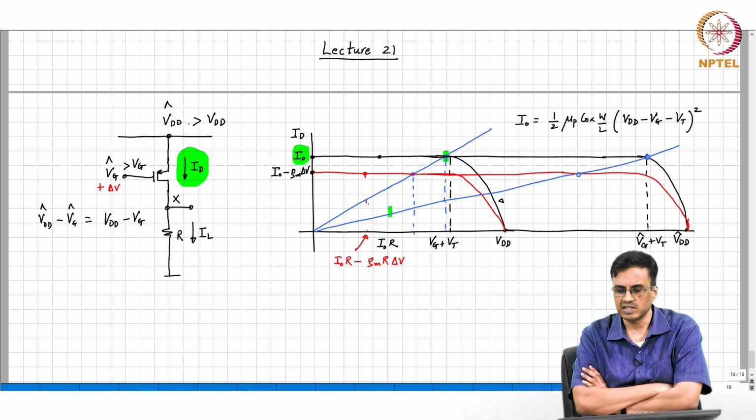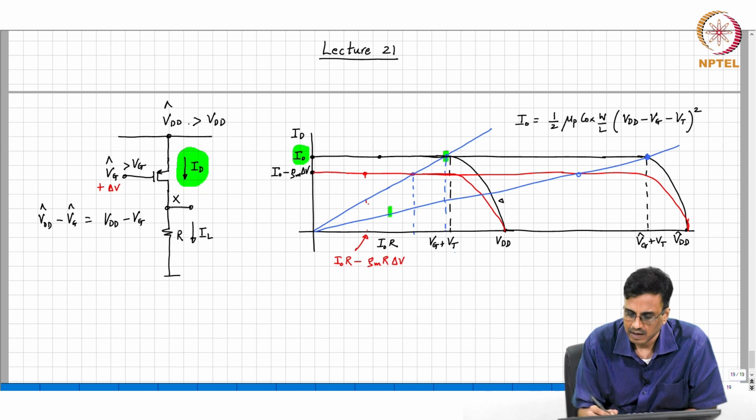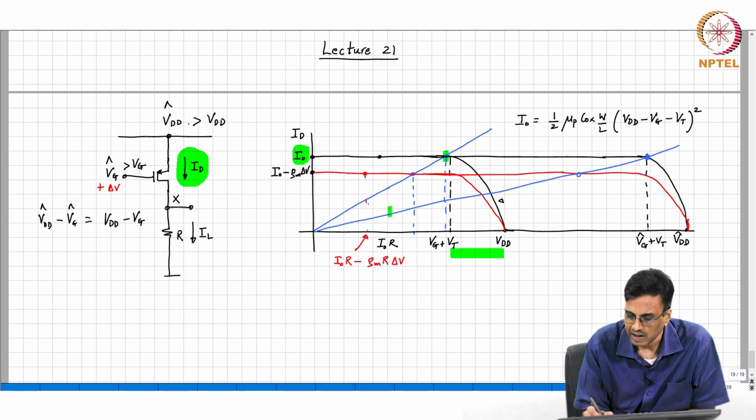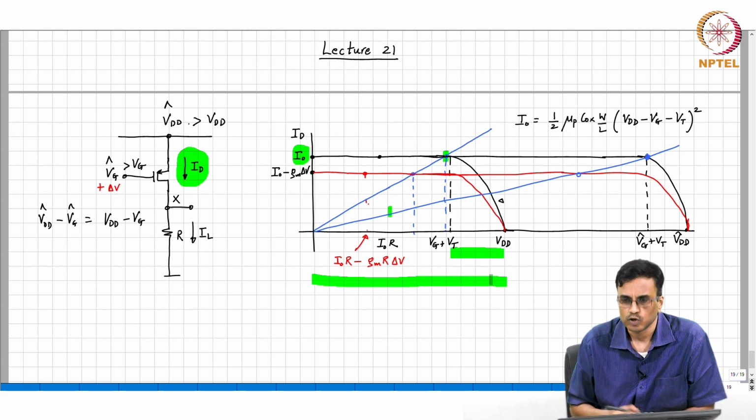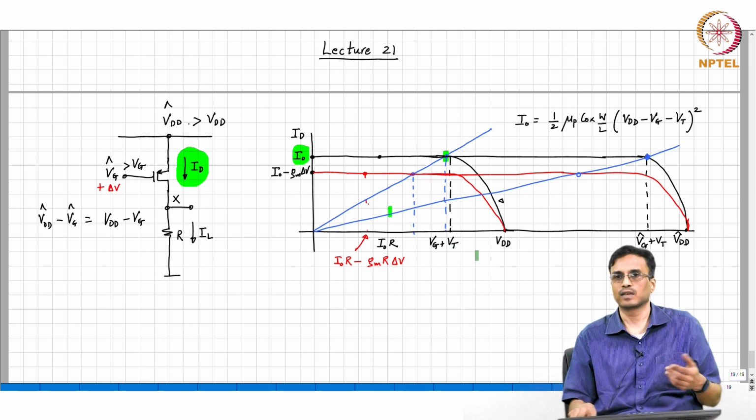So, in other words, originally we had some VDD, we had some maximum incremental gain, correct. Now, if I wanted to increase the incremental gain by a factor of 10, look at the picture approximately and tell me how much VDD must increase by. So, if you assume that VGS is very small compared to VDD, what does that mean? That this is very small compared to that. So, using that approximation, what comment can you make if you wanted 10 times the gain?